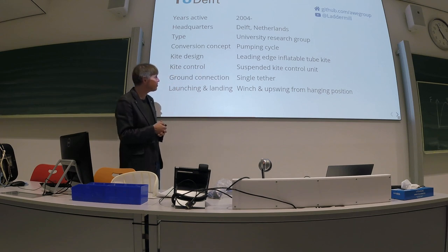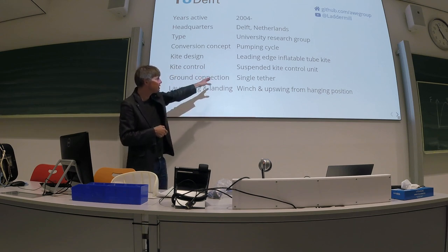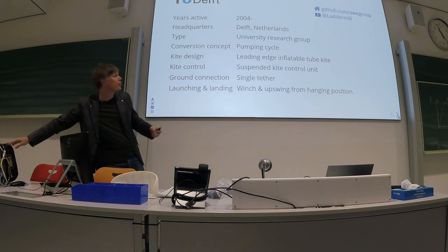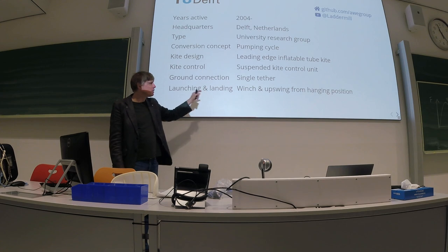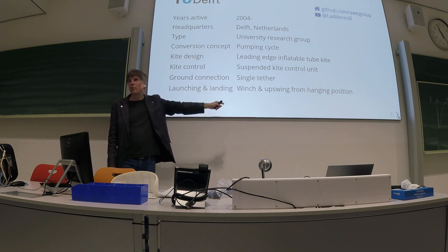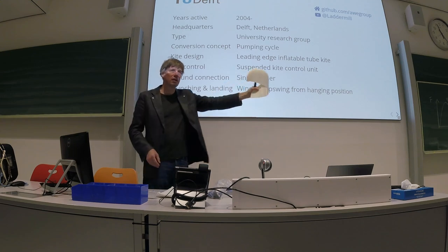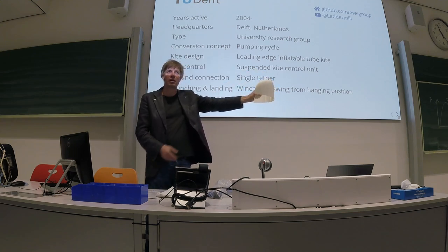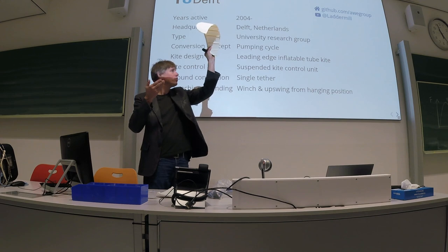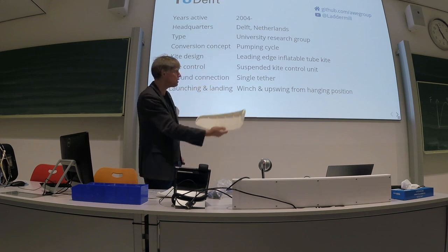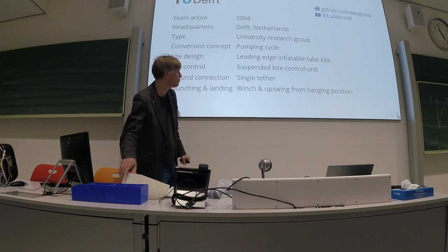We used the leading edge inflatable tube for pumping cycles with the suspended kite control unit, single tether, and we operated with classic winch launch, so positioning the kite downwind on its tail and then using the winch to launch the kite up, or from a launch mast in a swinging configuration.